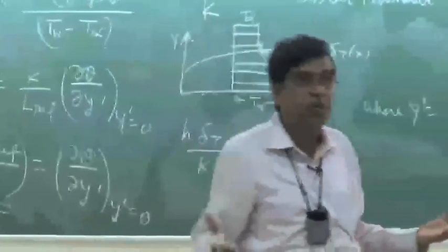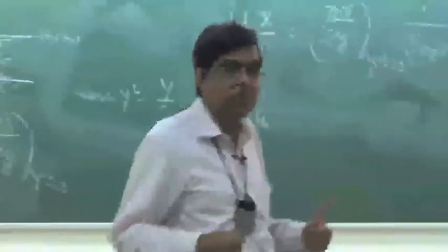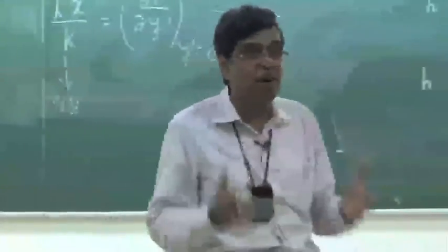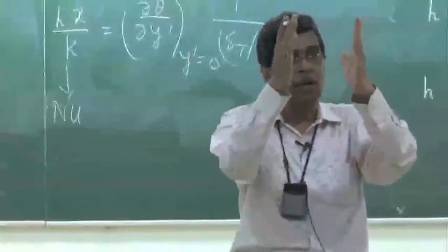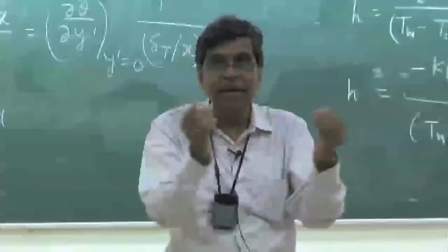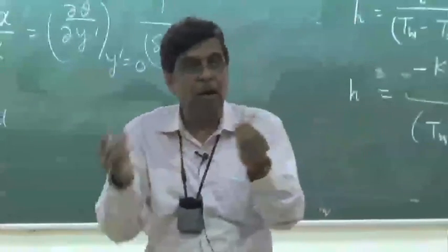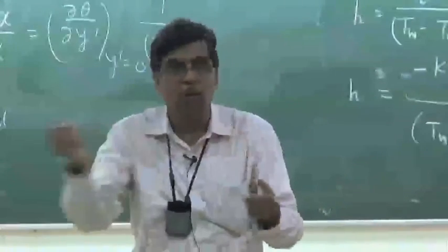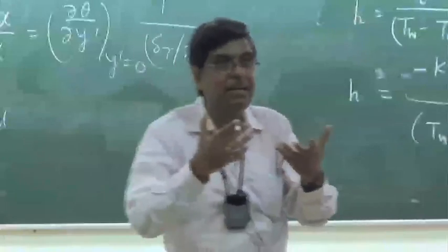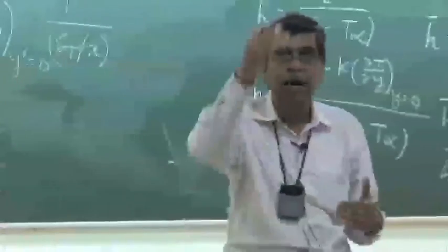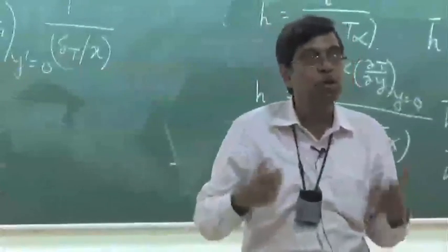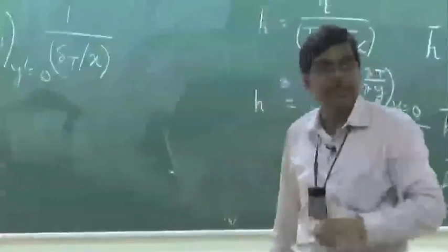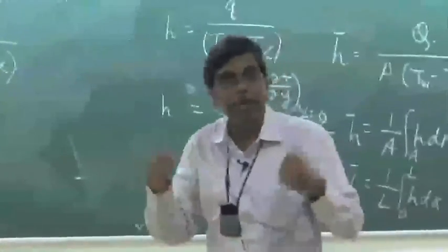What is the difference between the heat conduction equation and the energy equation? The energy equation is an equation for energy balance. In the heat conduction equation, we considered an element and made the energy balance by heat conduction coming in, going out, and energy generation, that's all. Or a convection heat transfer, which we took through only a convection heat transfer coefficient, and we made a balance.